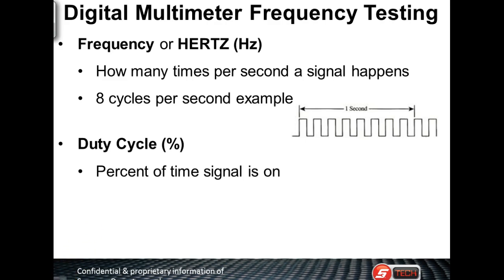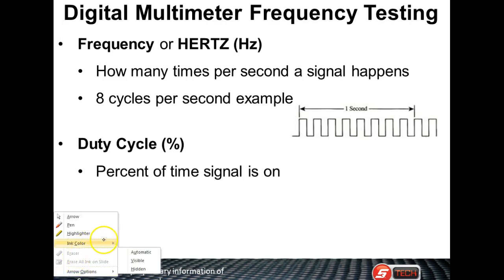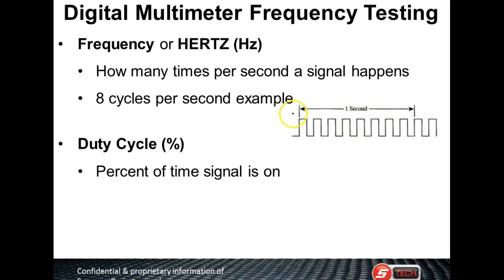If this right here was 10 volts. So let's say up here at the peaks, this was 10 volts and down here was 0 volts. What would y'all think the average DC voltage would be? Exactly 5, because the pulses are exactly the same. And that's exactly right. Well, what would happen if I came over here and made the positive pulse narrower?